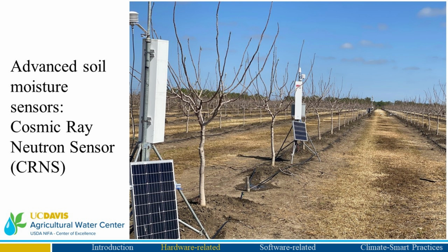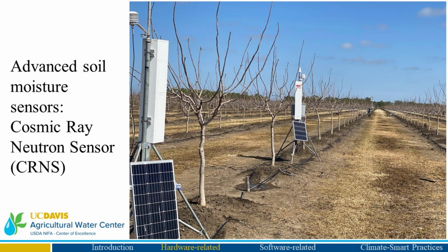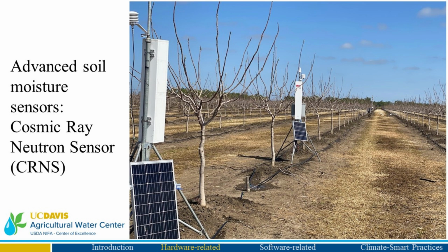And this is an example of those cosmic ray neutron sensors. They are not point measurements. They use rays that come from the cosmos. They come into our atmosphere, find aerosols. They interact with them, create a cloud of neutrons that reach the Earth's surface. And when they interact with the hydrogen in the water, they get slowed down. Okay? So that's the idea we use to measure soil moisture. And instead of getting a point measurement, you're getting a wide area, a circle of about 100 meters.